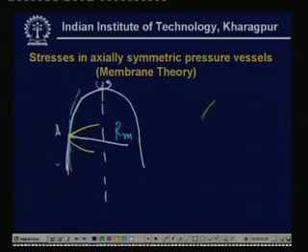Now, one is along this side, another is along that side. So, the radius of this will be here, because it has to be the same throughout. One can have a similar point here, and it will have the same radii. So, this will have another radius, and this is R t. So, we have two kinds of radii, one is R m, this is the meridional radius, that is the radius along the meridian, and this is R t. Definitely, most of the time R t is smaller than R m.